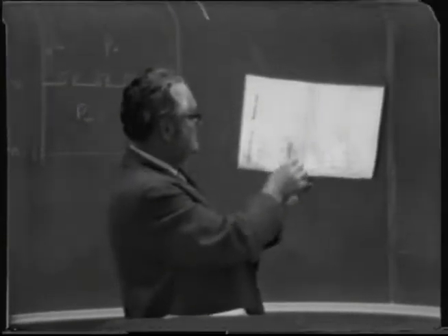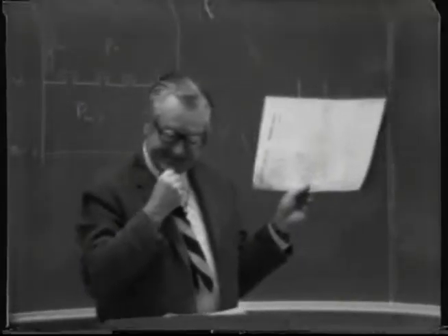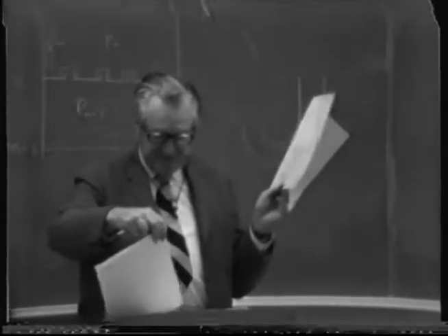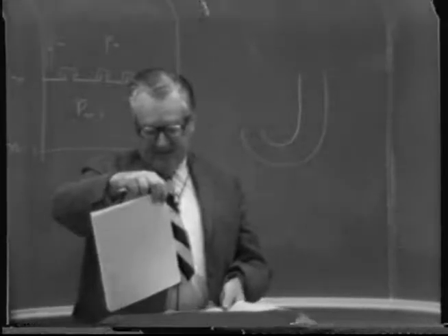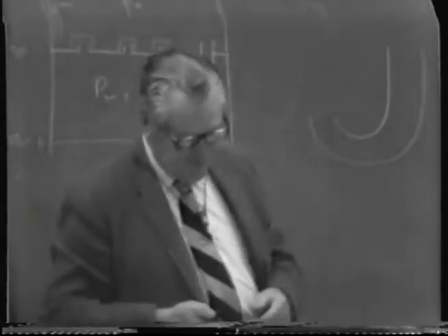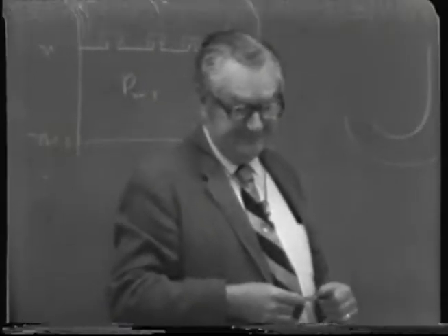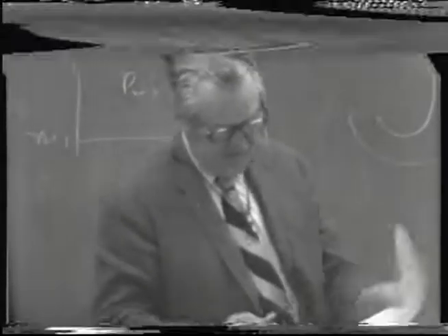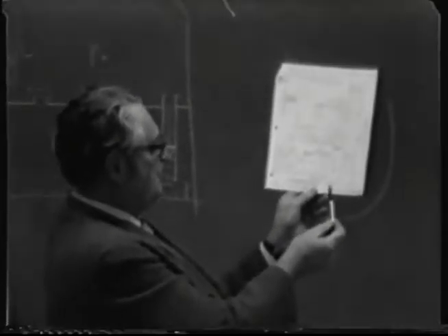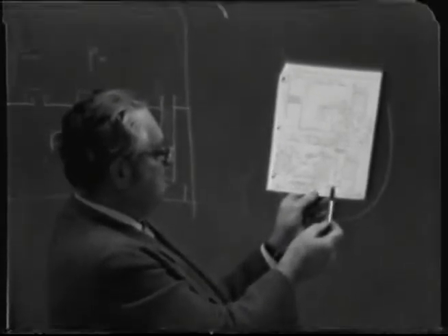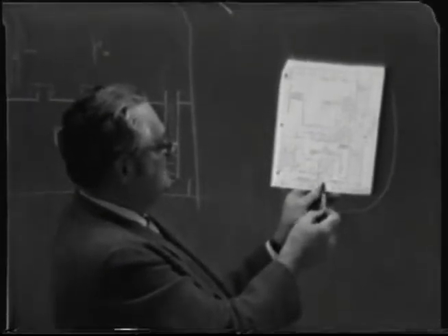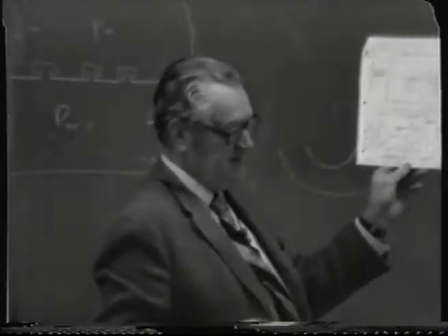It's a rather large type of apparatus, but it is a method of preheating the feed by, again, flashing off vapor from the stillage, where this vapor is mixed directly with the feed. So now if you refer back to this little sketch here, maybe we can get the principle. Stillage flows out here, the bottom of the stripping column, and into the bottom of this preheater device.